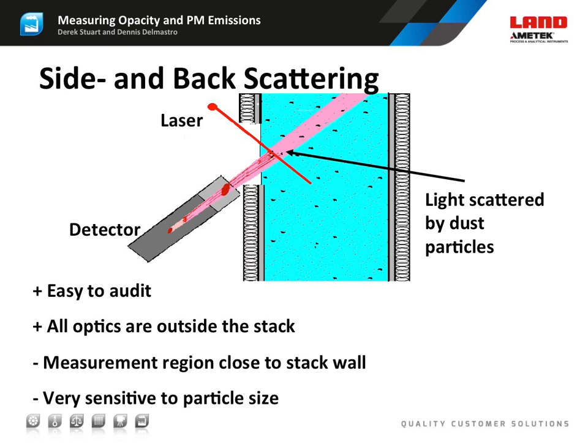However, the physics of the scattering process mean that these configurations are less sensitive, and they're also more prone to changes in particle size. The geometry means that the measurement region is close to the stack wall, so it can be difficult to ensure that the measurement is representative of the bulk particles in the process.